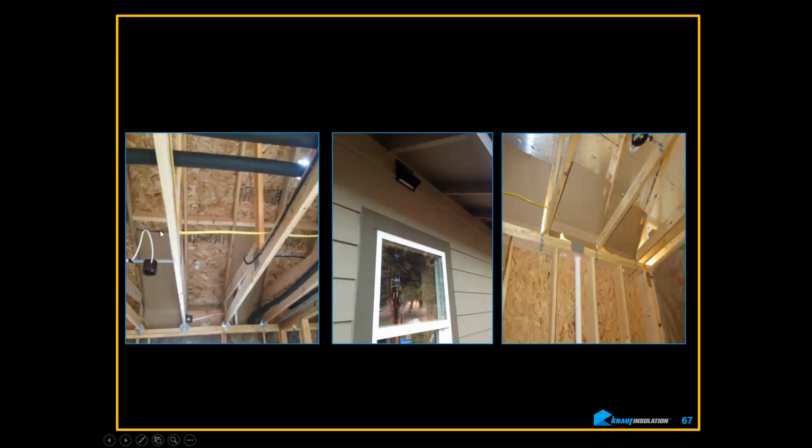Again, baffles installed incorrectly. This one's almost all the way up tight here. This is useless. This one I can't even see. Don't forget, there's blocking across there to prevent any kind of ventilation. Why didn't they just cut this down 1.5 inches, or do it on the flat? If they did it on the flat, they'd be better, but they'd still be blocking their 1.5 inches. So bad detail, bad design. There's got to be a better way to do it.